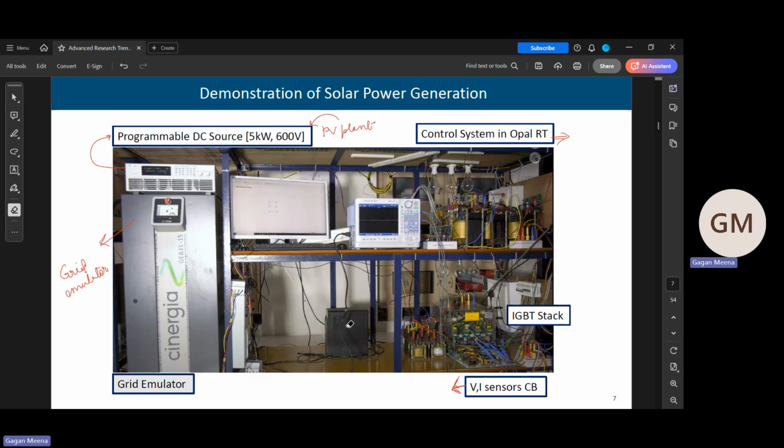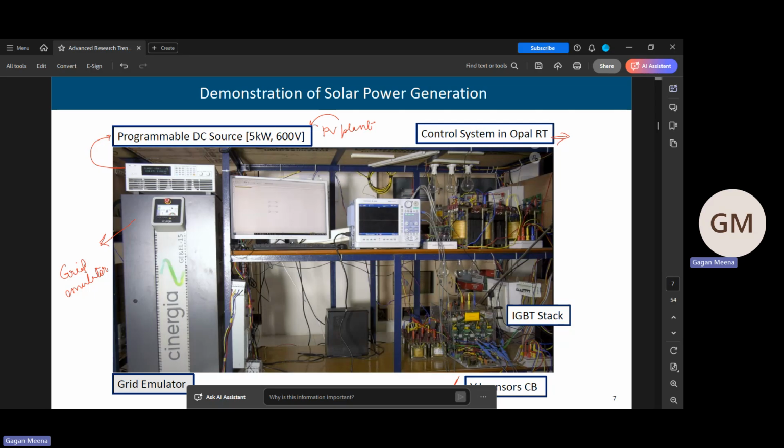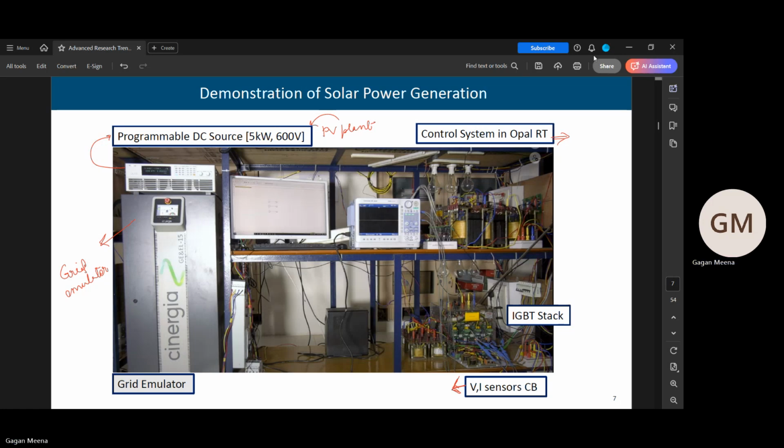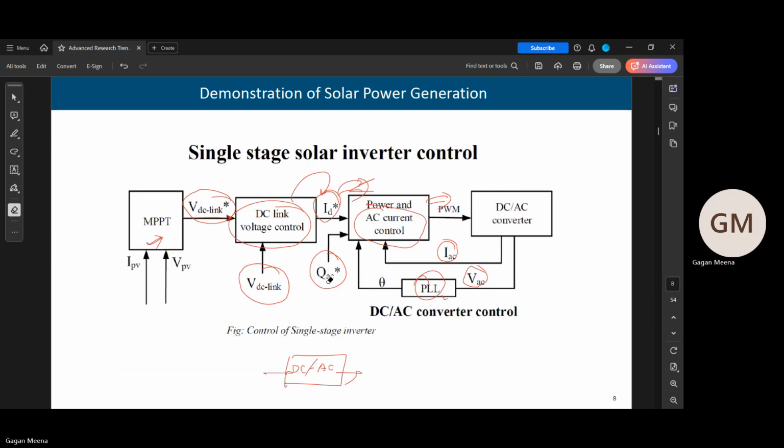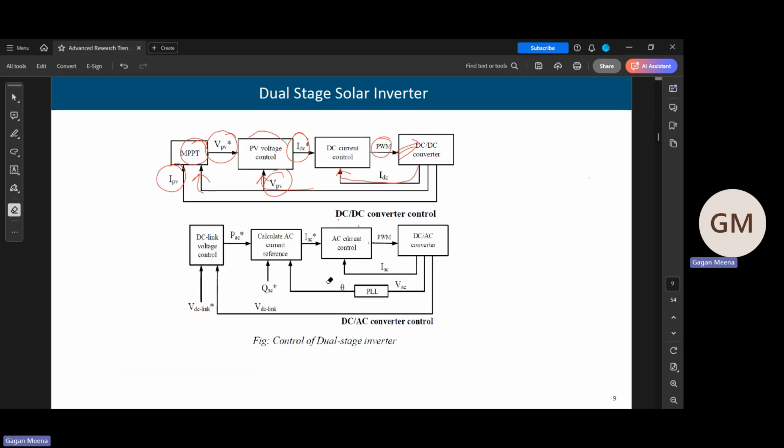The bleeder resistor is to bleed the excess charge. It removes the excess charge from the capacitor when it is not in use. And the snubber circuit is to protect against high dv/dt, a high rate of change of voltage, sudden changes in voltage. So for that, the snubber circuit is used.